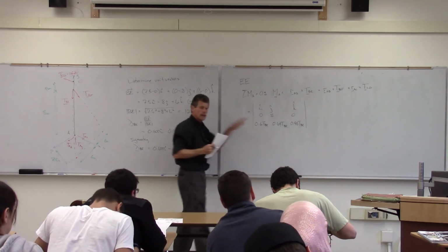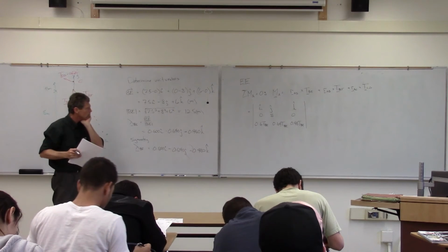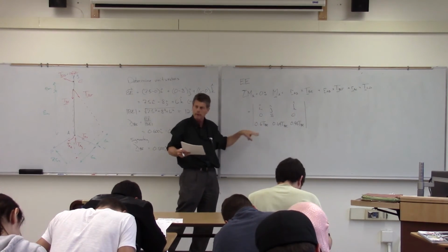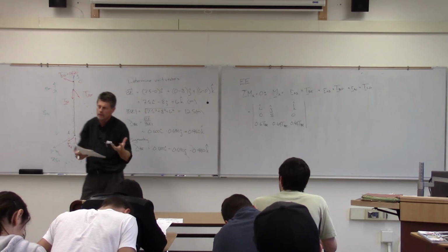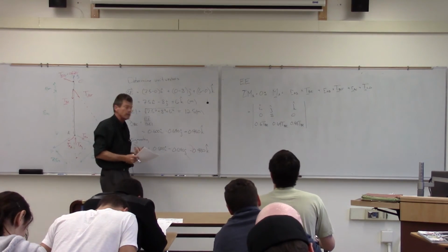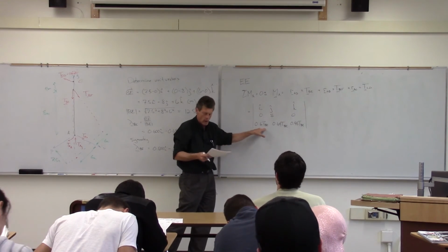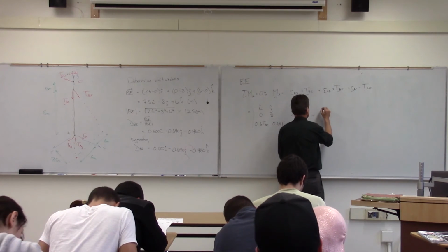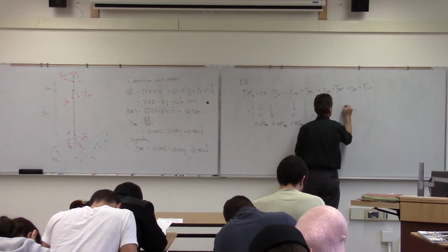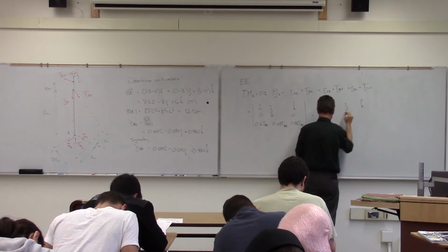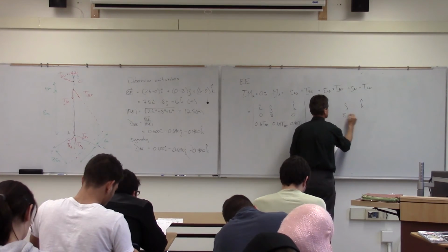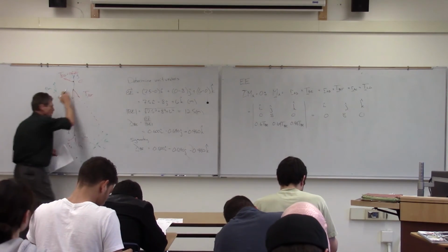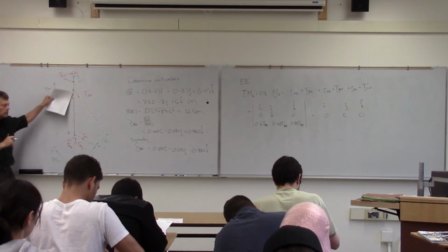Now the interesting thing, that's my first piece there. But notice the only unknown in that whole thing is BE. We're talking BE, but we're multiplying it times that unit vector. So we're looking at the various proportions of it going off in the x, y, z direction, but it's still one unknown in that equation. Similar equation for BF. This time I'll make sure I have enough room. My position vector I didn't talk about, but it's pretty straightforward. It's just 8 feet up in the y direction from A to B.